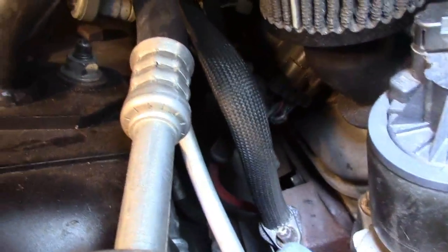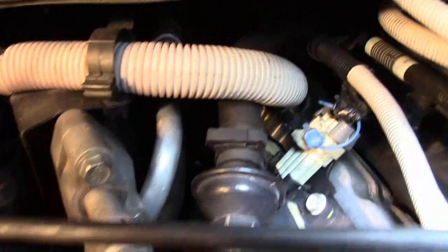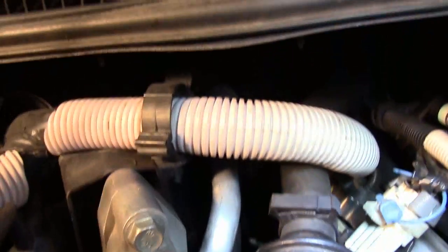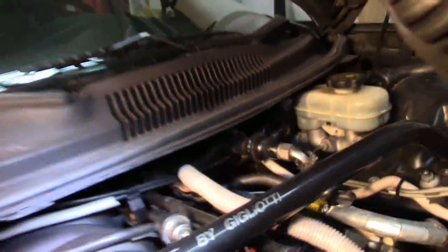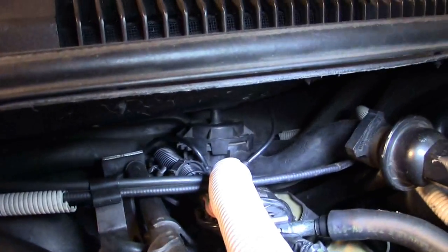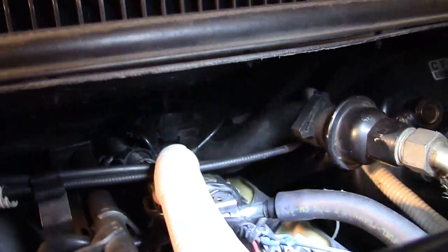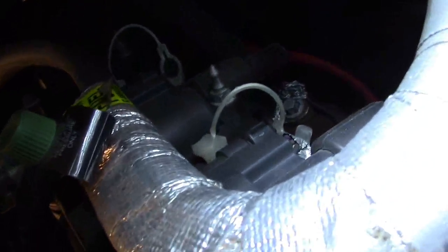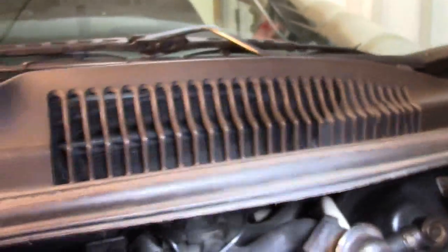Now let's look at this other tube right here, and let's follow it. And it goes to what clearly, right here, must be a check valve. And then if we follow back behind the cowl, it rolls back over to here, and it ends at this UFO looking thing with two other hoses coming out of it. One of those hoses goes to what clearly is another check valve. And if we follow that, it goes to the other bank on the exhaust manifold ultimately. So obviously this is our air system.